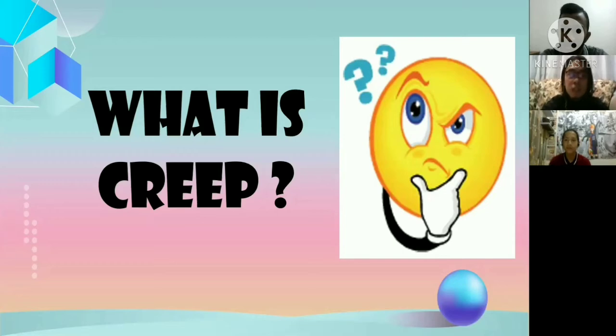Okay, so now allow me to begin this forum by telling you a little bit of background on creep. The definition of creep is that it is a slow and progressive deformation of a material with time at constant stress, meaning a material that is required to hold a load over a period of time will experience creep until failure, which is then called creep deformation. There are three stages of creep, which are the primary stage, secondary stage, and the tertiary stage. These stages represent the characteristics of the material under the influence of creep at different times.